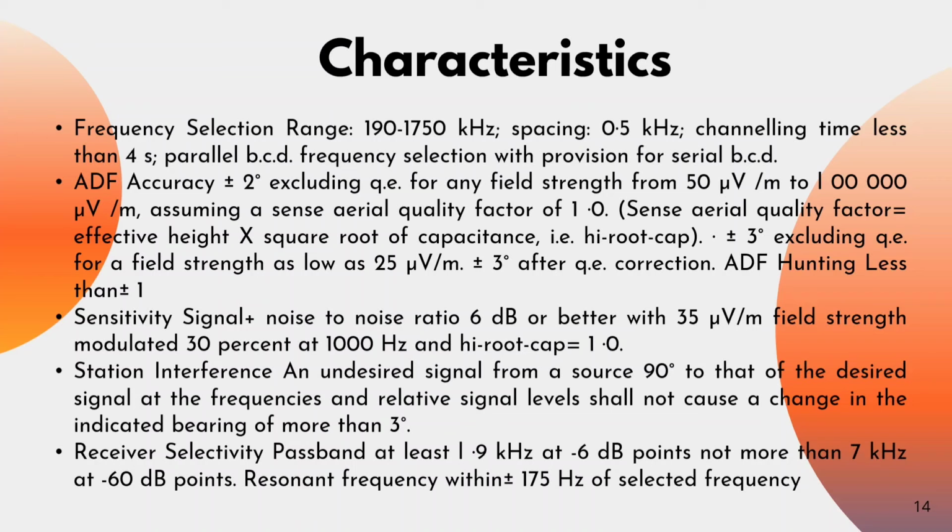Sensitivity: signal plus noise to noise ratio 6 dB or better with 35 microvolts per meter field strength, modulated 30% at 1000 Hz, and sense aerial quality factor equal to 1.0.